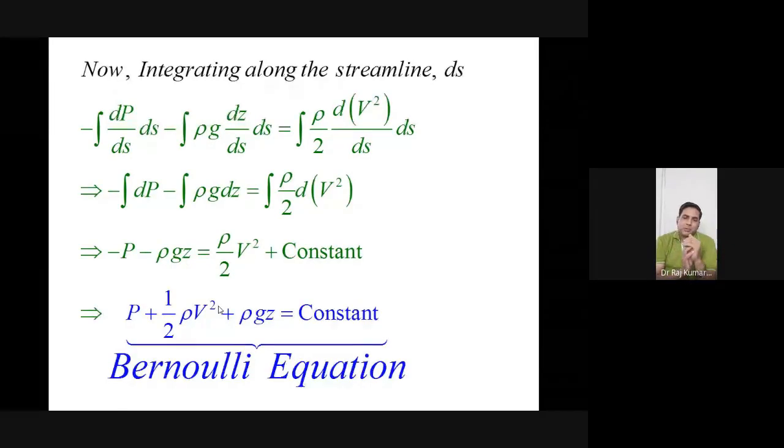No matter how genius or how expert a teacher, professor or researcher is, everybody does the initial calculation from Bernoulli only, because this will give the idea of what my value should be in the most general case. I am neglecting everything, I'm just talking about the ideal way. So this is the first starting calculation.